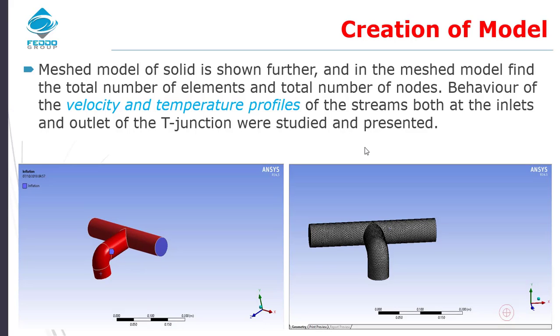So by the mesh independent study, basically you go to our mesh, then you readjust, probably reducing the mesh sizes. You would agree with me that this is hugely dependent on computational strength, on the power of your computer. The more computational strength you have, the finer the mesh you can use, and the more reliable your result will be.